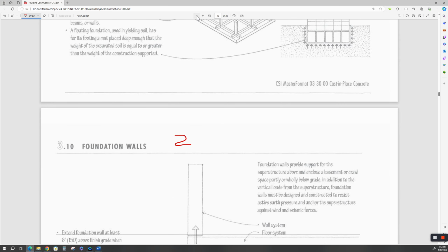But again, that can be a blessing or a curse. The benefit of the crawl spaces is all your plumbing and everything can be underneath here. So you don't have to worry about 30 years from the house being built having to reroute the plumbing outside because the slab has settled a little bit and you've got a belly in the pipe. You can come in here and repair the piping or whatever. And you can also adjust the level of your house under the crawl spaces. So again, that's a blessing and a curse.